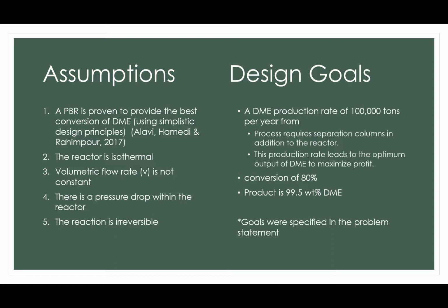The assumptions we made are that the PBR is proven to provide the best conversion of DME. The reactor is going to be isothermal, but not isobaric, meaning the volumetric flow rate will not be constant and that there is a pressure drop within the reactor. The reaction is also going to be assumed to be irreversible.